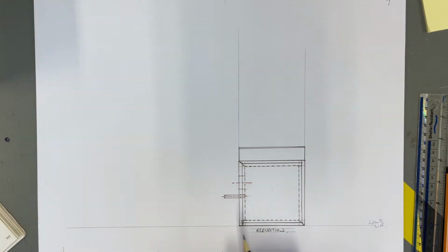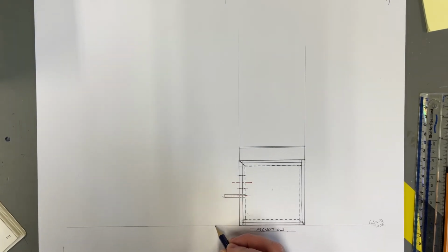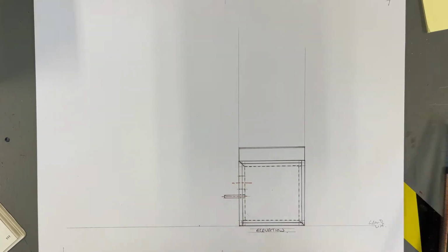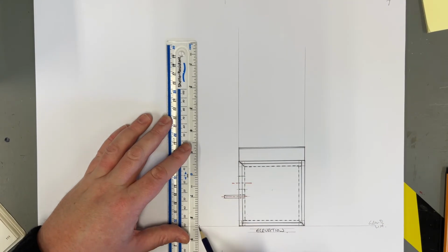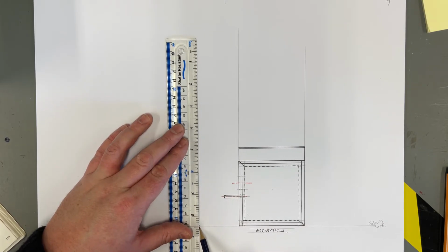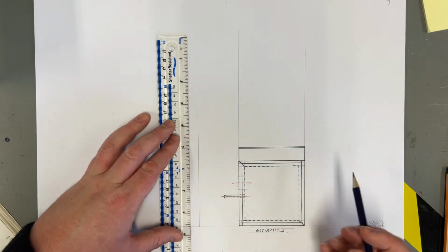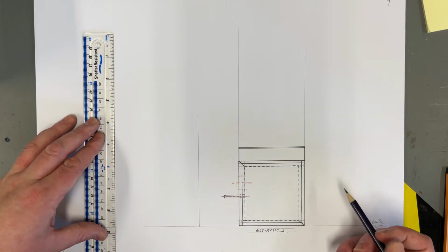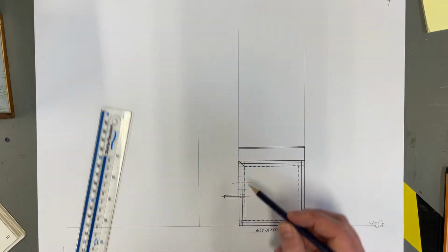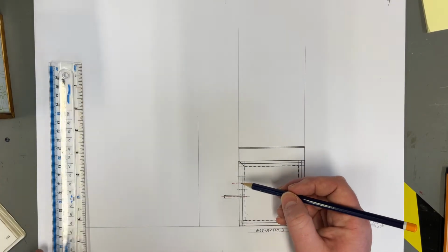Come down to our sheet of paper, and what we're going to do is leave a little gap, enough room to put the dimensions in, and I reckon just roughly about there would do. And then again, project up a construction line. In this instance, you don't need to go all the way, just let's go up to about that sort of height there. And we'll decide that that is, in fact, this corner, this edge of the object.